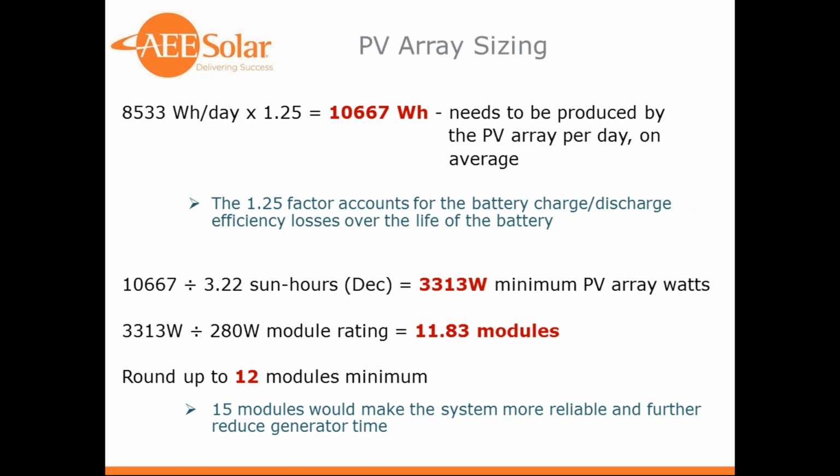So typically you use 3 standard 60 cell modules in series for a 48 volt system. So the number of modules really needs to be in multiples of 3. So you can do 9, 12, 15, or 18, but not 16, for instance, with those charge controllers. There are some controllers that do different voltages, either higher or lower, but generally we use standard modules in groups of 3 with these off-grid designs.